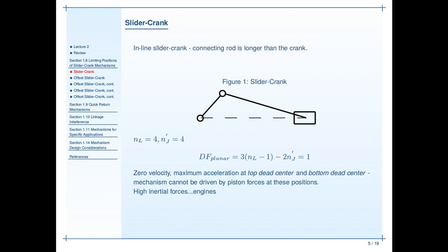This has an interesting effect, or something to think about. When we look at single-cylinder engines, we often look at it from the standpoint of a force being generated at the end of the piston due to the explosion of a mixture of fuel and air. That explosion, though, if the piston is truly at top dead center, can't really put anything into the mechanism. It won't be able to move. Hence, we often have a flywheel to maintain motion, so that as the piston carries around, we actually get movement.